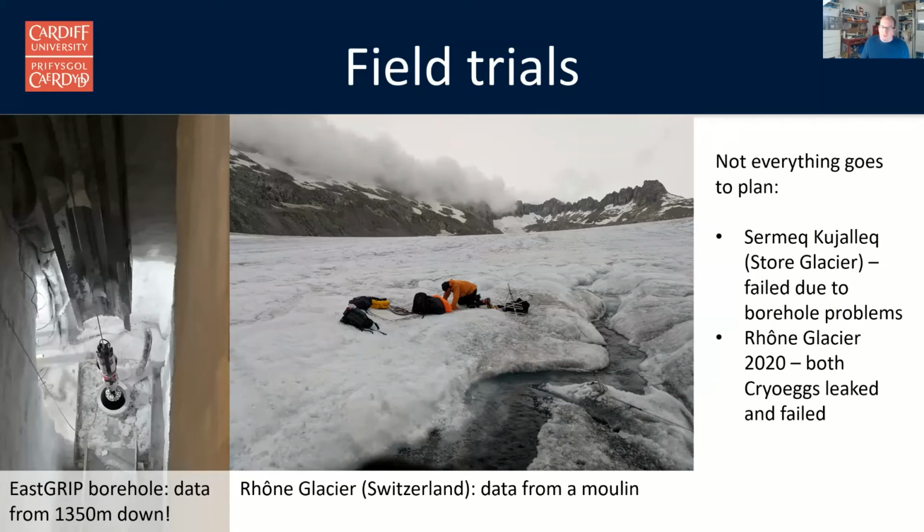And we had a trip back to the Rhone Glacier at the last minute this year when coronavirus restrictions were briefly lifted. We went dashing off to Switzerland to try and do some experiments, but we had big issues with Cryoegg leaking. It turns out that the assembly process, I basically got lucky last year with pouring the adhesive sealant into the instrument and got a good seal. This year I did it slightly differently and it didn't work. So there's definitely more work to be done.